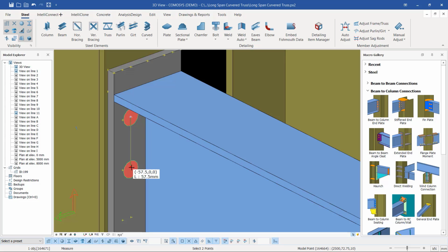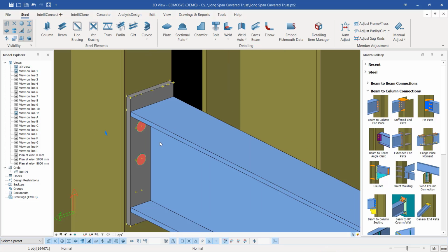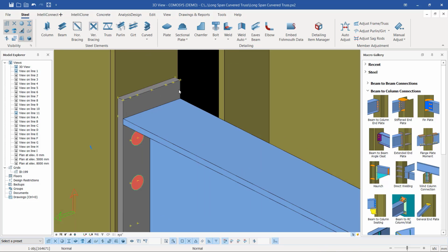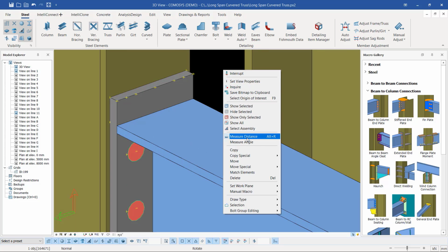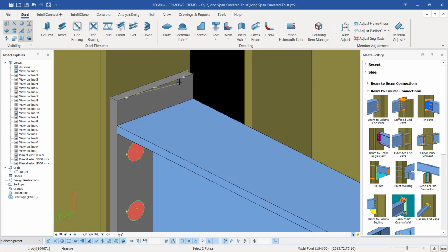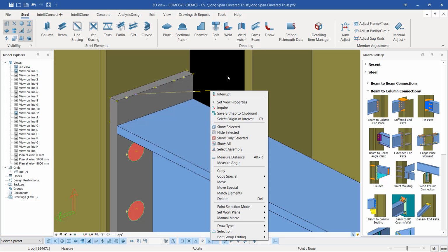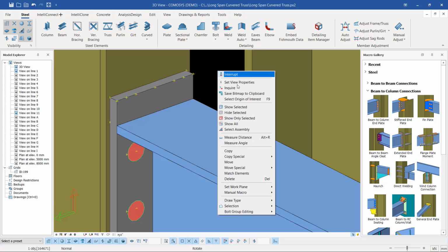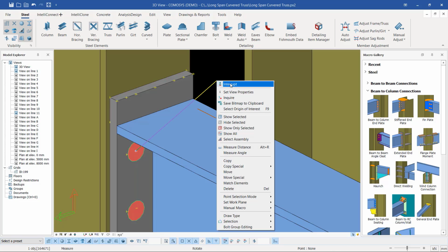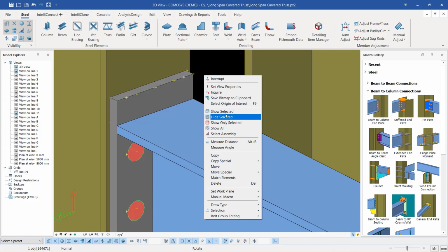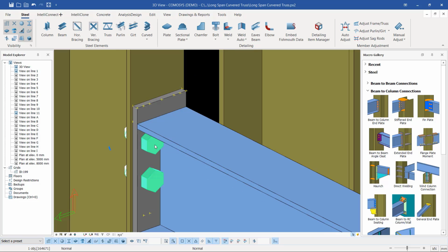Prior to snapping on any, you can see we have 57.5. That will be the dimension we will be applying. We also want to confirm this between this and that. Right click and come to distance, and I want to confirm this and that is 45.5. Remember, this is 57.5. Let me terminate that command and confirm from here to here, that is 57.5. So if I bring back my bolts here, show all, and double click on the bolts